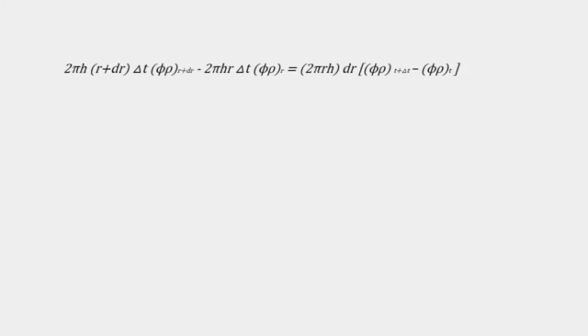Again, we are finding the equation of mass conservation, but this time in radial flow. So this is the formula for mass in, where flow rate is substituted with area times velocity, and area is further expanded using the area formula of radial flow. Steps are repeated for mass out too. The volume of control volume is differentiated in terms of radius, and then delta R is moved to the right and substituted in the mass accumulation formula. The final equation of mass conservation is derived as following: mass in minus mass out is equal to mass accumulation.